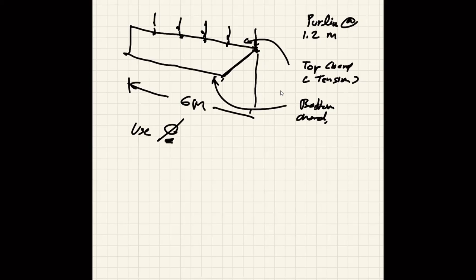So you may choose to check this one with the entire length, and the K is equal to 0.65. You better check that again. And then the shorter one, in plane, it's going to be shorter and K equal to 1. So that will be more critical.